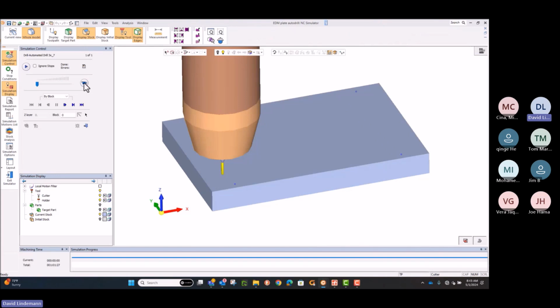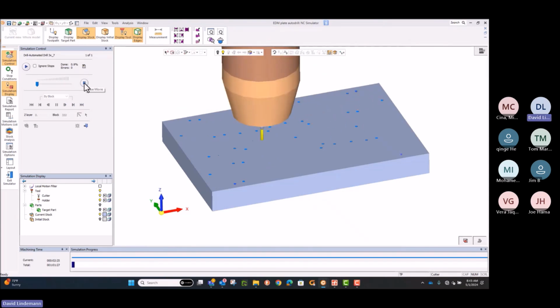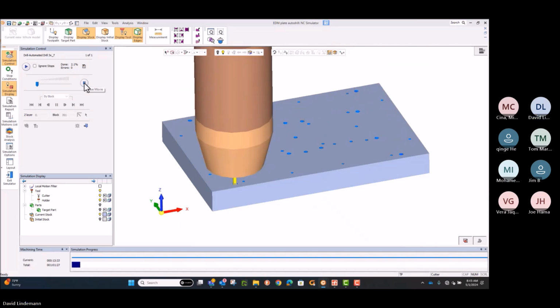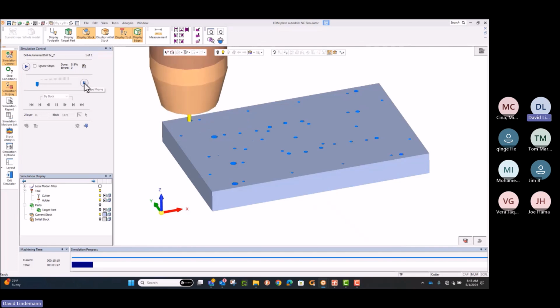And there we go. Same simulator as before. So there's all the holes with the spot drills. Now I'm coming back with another drill that is used in multiple places with different holes. Now you see me doing some circle mill patterns, working my way down. So I can use that same end mill on different size circle mills. It's just, again, a matter of what I set up in my sequences.